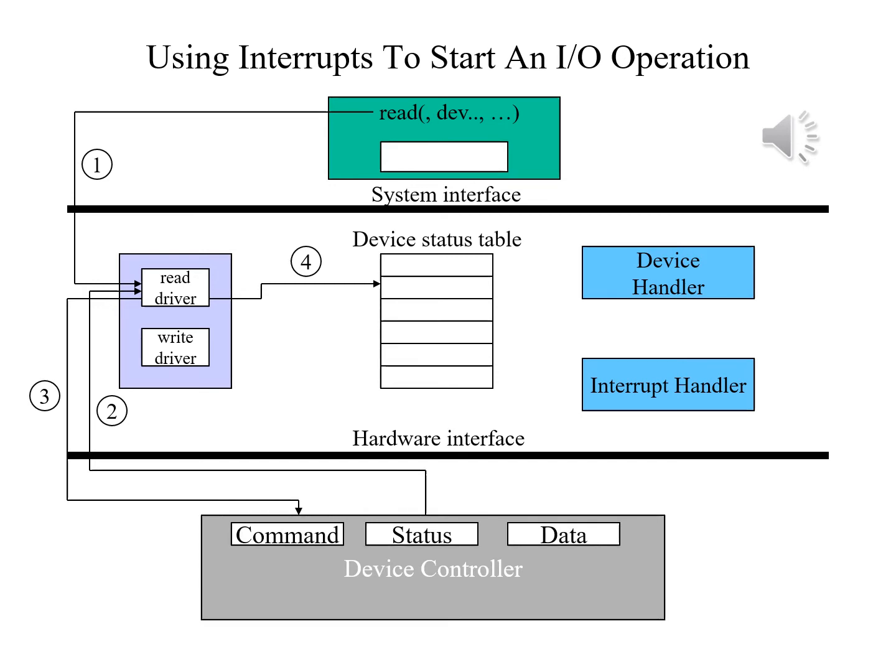Interrupt-driven I/O works on the principle that instead of constantly checking the device, we will wait for a signal from it. That signal is called an interrupt because it is interrupting whatever the processor is doing. If I were still trying to make tea while trying to work, it would be analogous to putting a whistle on the tea kettle. I no longer have to keep checking the tea kettle because I am confident that the whistle will get my attention.